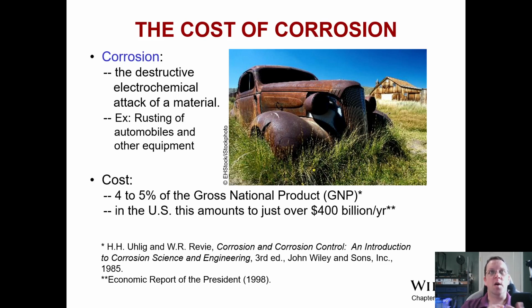Corrosion is the altering in a destructive manner of a material. It's no longer able to perform its original function to the same degree. So what we see here is an attack of rust on a material, in this case steel, and rusting of automobiles and equipment, all different types of metallic structures, especially ones that their coatings have burned off or been worn off or eroded over time. Those are able to rust. Interestingly, in a material like that, once it starts rusting, yes, it is a continual process of rusting, but the actual surface corrosion rate slows down, and we're going to talk about that later on.